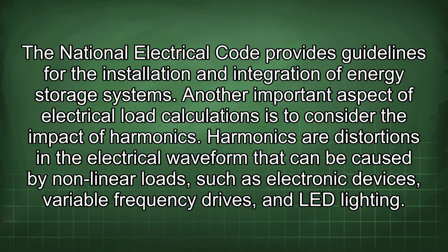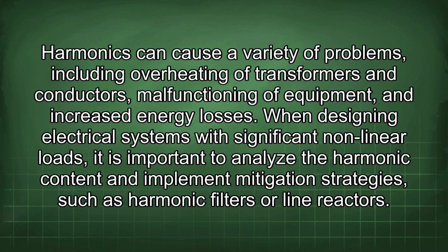Another important aspect of electrical load calculations is to consider the impact of harmonics. Harmonics are distortions in the electrical waveform that can be caused by nonlinear loads such as electronic devices, variable frequency drives, and LED lighting. Harmonics can cause a variety of problems, including overheating of transformers and conductors, malfunctioning of equipment, and increased energy losses.